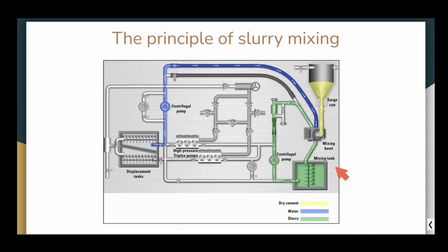After the fluid flows to the mixed tank or mixed tub, the centrifugal pump takes it and discharges it upward again to the mixing system, and it goes also through the densitometer to measure the level of density of our cement fluid.